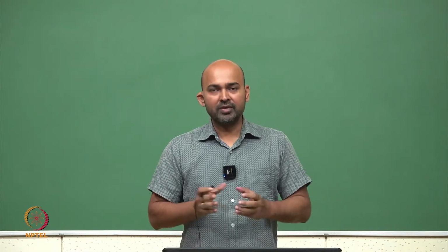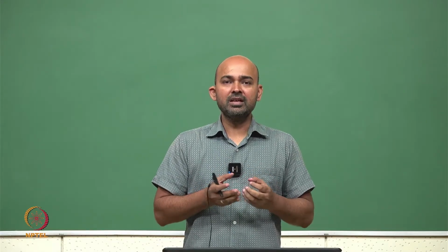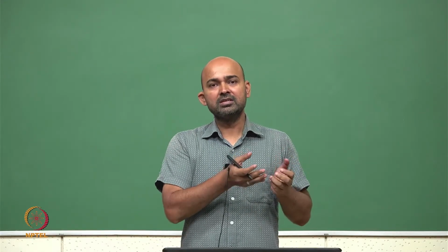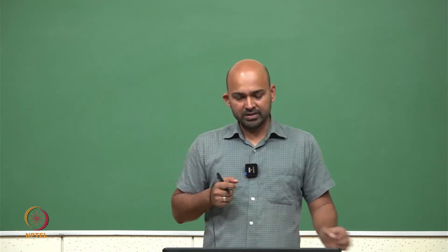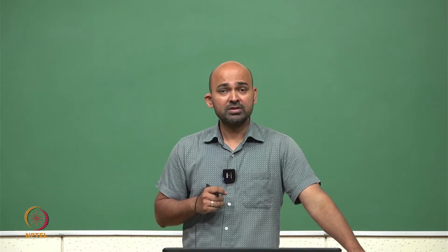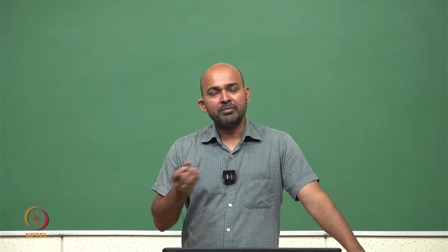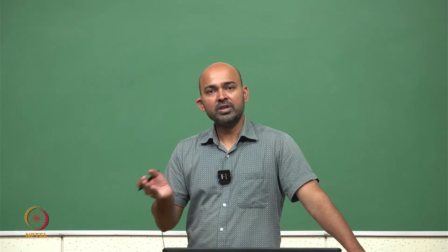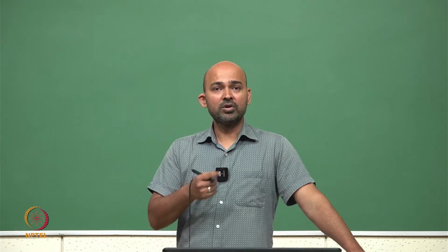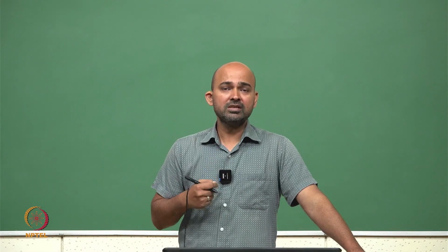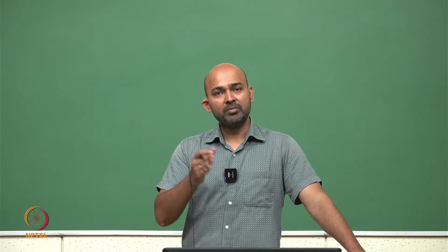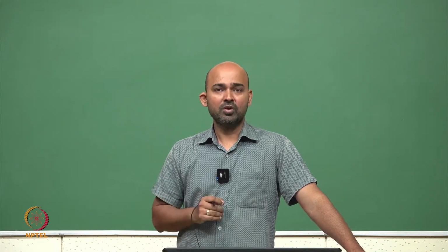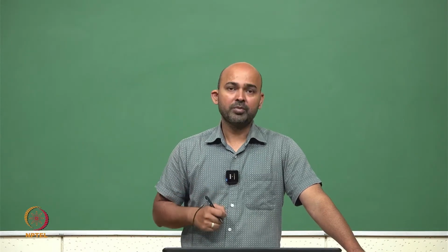Last lecture we saw one example where we took the summing amplifier. This circuit will add up 4 signals V1, V2, V3, V4 and produce the weighted output of these inputs. We can have a simple algebraic sum V1 plus V2 plus V3 plus V4, or depending upon the resistance values we can choose all these resistance values in some ratios and produce the weighted sum as well, V1 plus 2 V2 plus 3 V3 and so on, whatever we want to provide.